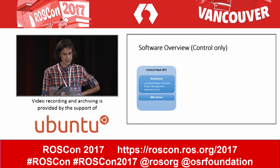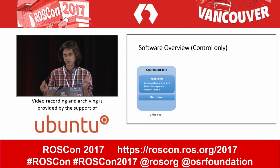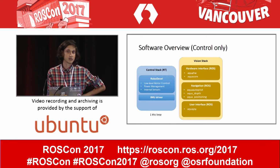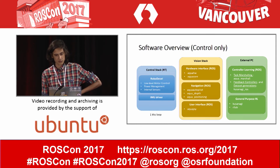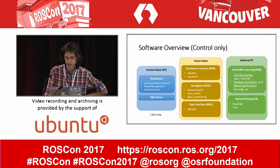So I'll talk a little bit about the software that we use for control. We have the control stack that is running a 1 kilohertz real-time loop. This is what interacts directly with the low-level sensors and the motors. Then we have the vision stack where we drop all our ROS software: some ROS interface for the hardware, some ROS packages for navigation, and some packages for user interface. And then another big part of what I'm going to be presenting today is our controller learning architecture, which is also built on top of ROS.